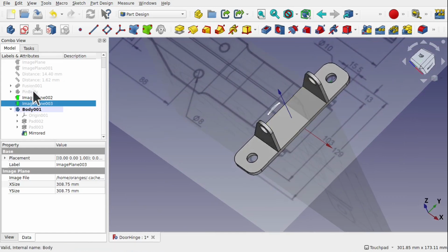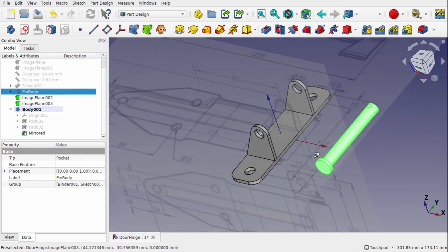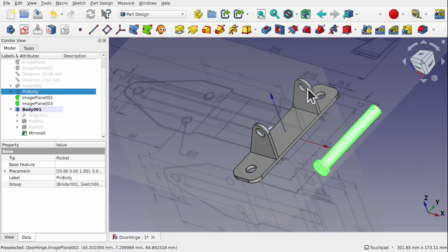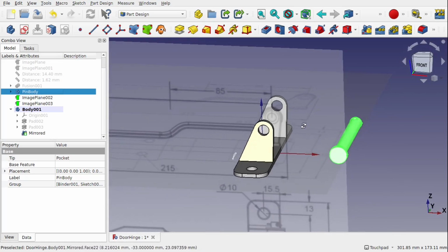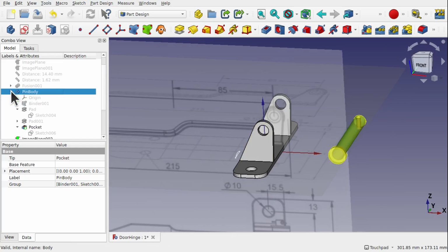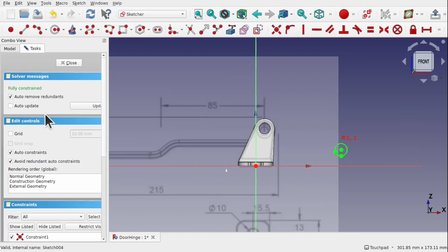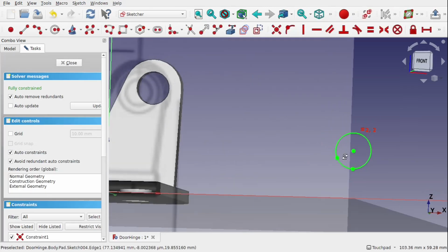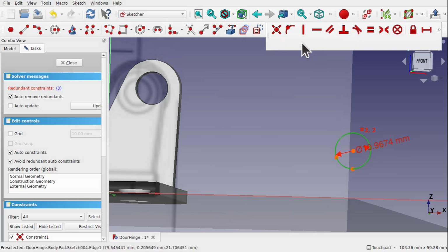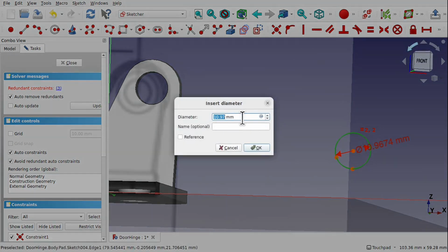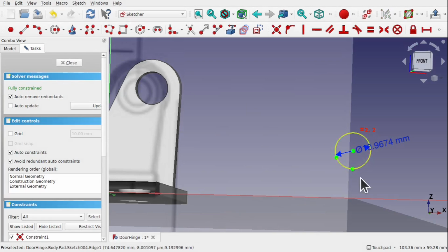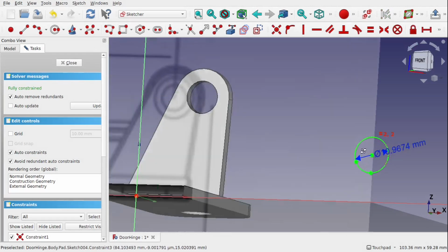Let's have a look at our pin. So we've got the pin body, and the diameter of this pin should fit in here. We'll need to check that. Let's come back into the pin, and the sketch, this circle, double click it and come in. And if we wanted to, we can come in and add a dimension in here. So it's 10.97, and place that as a reference. So that gives us a reference dimension. So this hole has to be larger than this reference dimension.